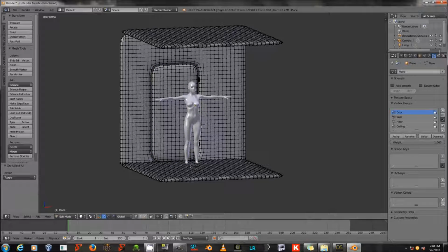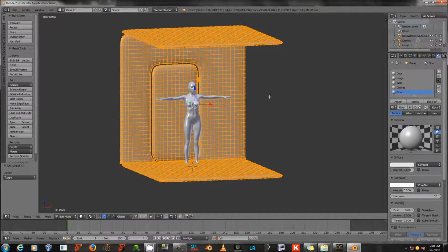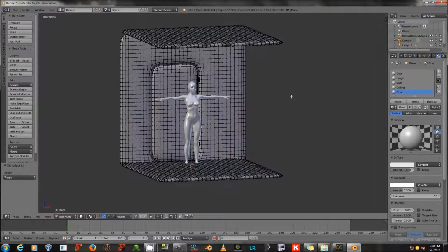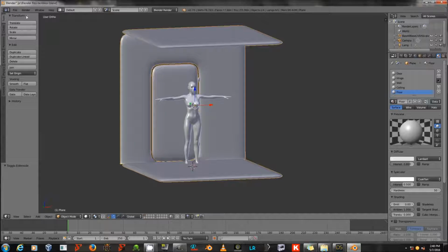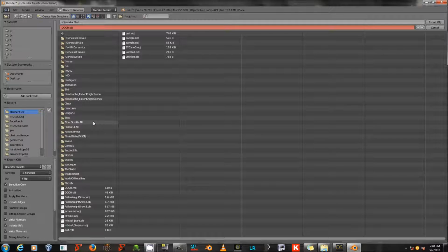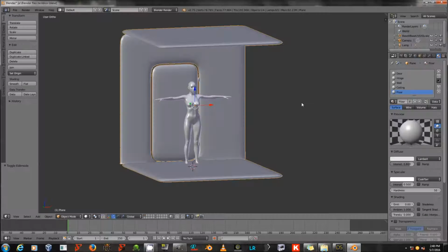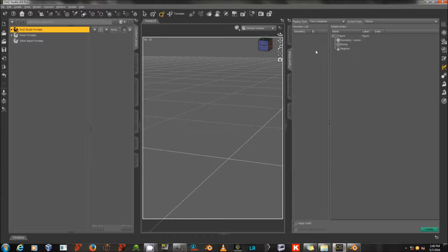And you need to have your material zones set up and your UV projection already done before export, all your material zones finalized. And then you export to a Wavefront OBJ at whatever scale you like. I operate on DAZ Studio's scale because Blender's scale presets are more or less broken in DAZ Studio, but that is up to you. You need a Figure Setup tab in DAZ Studio to start working with this.